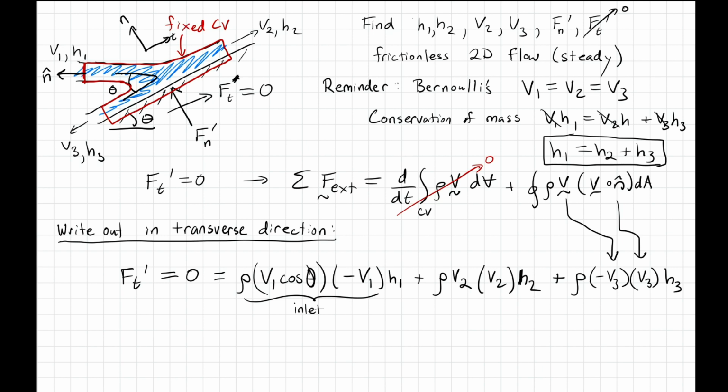All right, so if we put that all together, now remember that the velocities here are actually all equal, we found out. v1 equals v2 equals v3. So in fact, a lot of these velocities are common to each term. So I've got a v squared everywhere and a rho everywhere. And so if I cancel that all out, and in fact I'm going to move h1 to the other side too, then you can write that, so I'll cancel common rho times v squared.